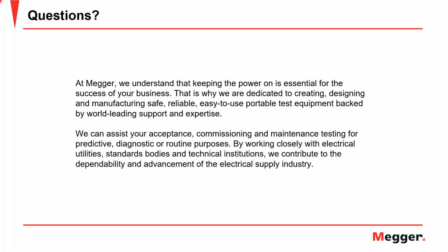An example to elaborate on that further would be, let's say we have a ground distance protection, and basically this ground distance element uses your residual current as your operating quantity, right?